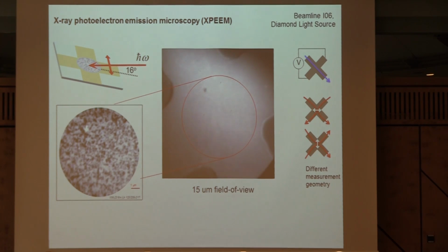So this is the actual device and a magnetic contrast image taken from the beam. In this case, we're using a slightly different geometry than was used in the previous experiments because of the limited number of contacts in the beam. Here we have a cross, and we achieve the orthogonal pulses by pulsing down 2 arms at once, and then the other 2 arms from the side, and this generates a net vector in the center which has the same effect. What's nice about this is you can also measure the largest and easiest signal electrically in parallel.